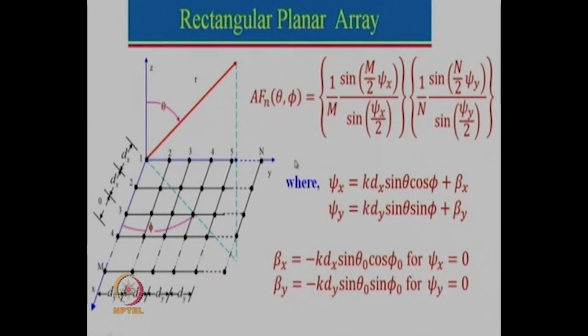So now you can apply the concept of the linear array, for which I have given you the expression. You know that for a linear array, a beam width relationship is there with the total length. From that you can find out the total length, and then you can see what is the number of elements required. As a starting point, you can take d as lambda by 2, but you can always adjust that.